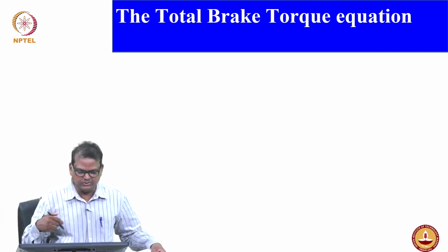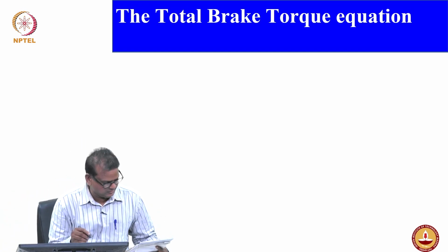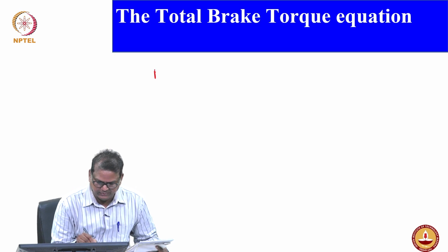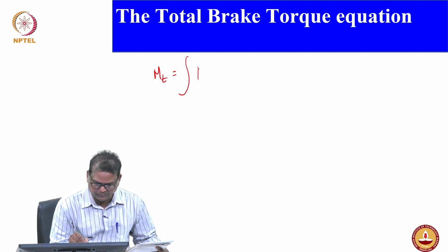The total brake torque, I'll make it MT. This is the general equation: MT equals mu dN r.